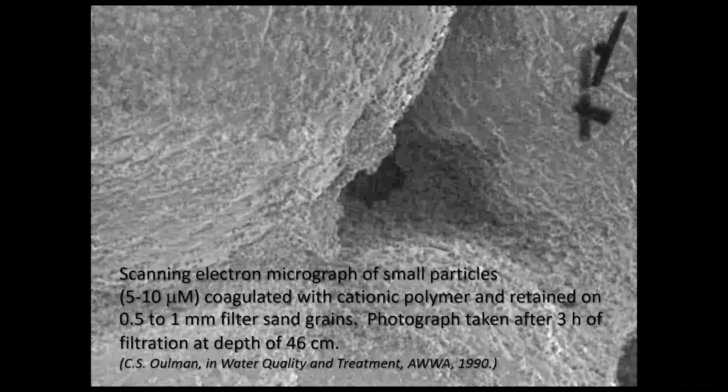When the coagulation is optimized, the particle removal can be optimized as well. However, even once you get to this point where your coagulation is optimized, you're getting great filtration, and all particle attachment is occurring, it's still susceptible to upsets. And that can be caused by sudden flow changes through a filter. If all of a sudden there's a big hydraulic event on this filter, a lot of these particles might become dislodged and move past the filter.